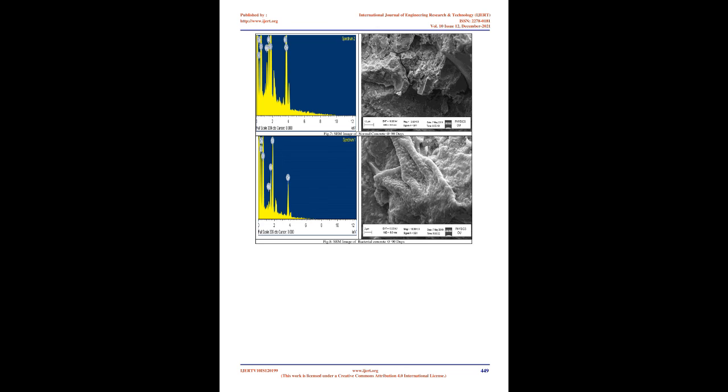compared to normal concrete. From the micrographs of figure 9 and figure 10, it can be seen that the increase in calcite content, in white color, formed on the surface and fly ash particles resulted in a more compact and denser matrix, filling the voids and cracks in the concrete and improving the pore structure of the concrete. Due to reaction of silica with free lime at later age, calcium silicate hydrate compound forms. Because of this hydrated compound, the values of compressive strength for bacterial concrete with addition of fly ash are higher at 90 days compared to normal concrete.